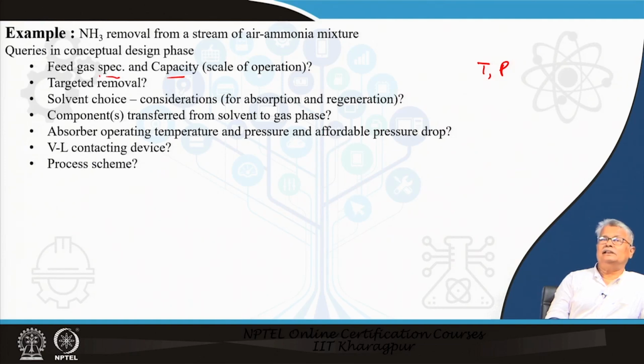We definitely need to have an idea that how much of this loss is going to take place. If my solvent is cheap, we may not bother, but if the solvent is expensive, we definitely would like to have some operating conditions or some arrangement where the solvent losses are kept to a minimum. There is one thing which is very important. The absorber is an equipment where I have two phases. I have the liquid, I have the gas which is coming in as well.